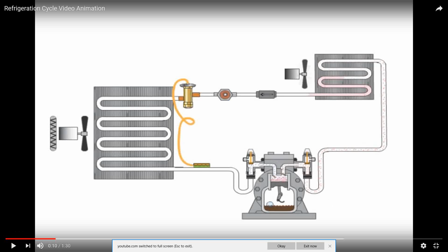So you could see if a compressible gas is compressed, of course the pressure gets high and also the temperature gets high. So this refrigerant vapor with very high pressure and high temperature gets into the condenser, and it just naturally rejects its heat to the environment. This temperature would be much higher than the outdoor environment, say like 30, 40. But as long as you have a higher temperature, you could release your heat to the environment. So that's what happens in the condenser.